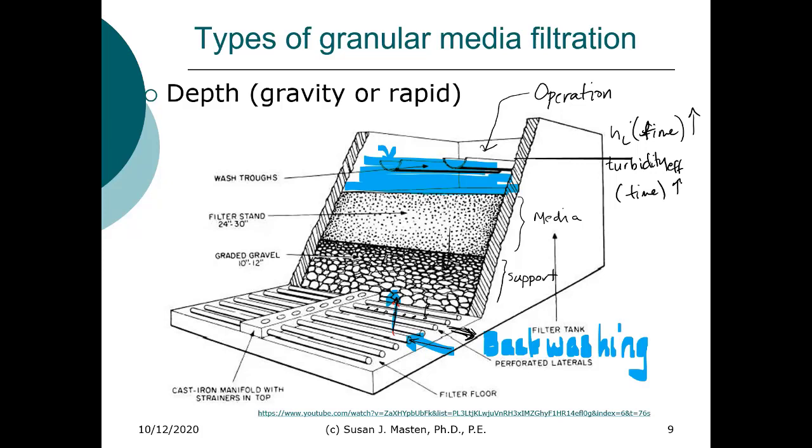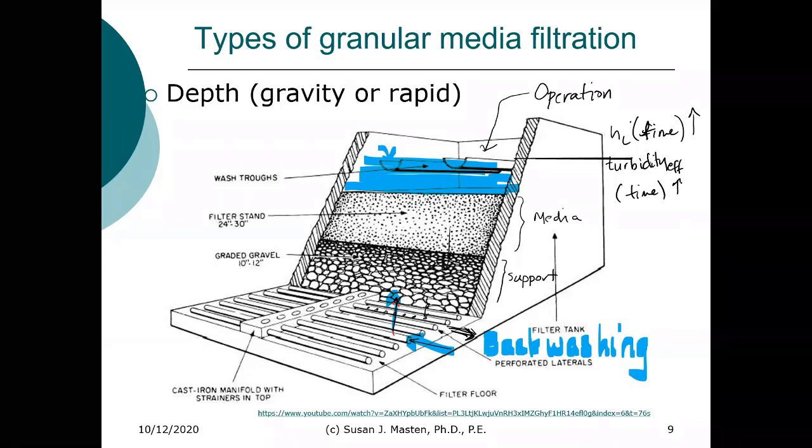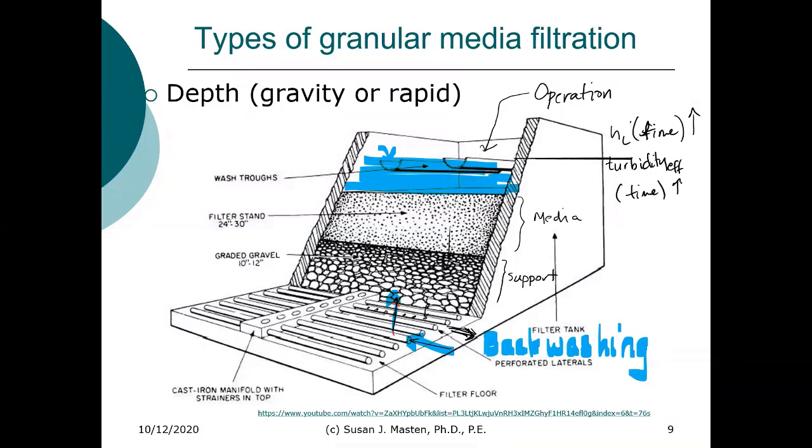In many cases, based on experience, backwashing will actually be done on a timed cycle, just based on knowledge that, for instance, every 8 hours it will need to be backwashed, rather than watching and then backwashing manually.